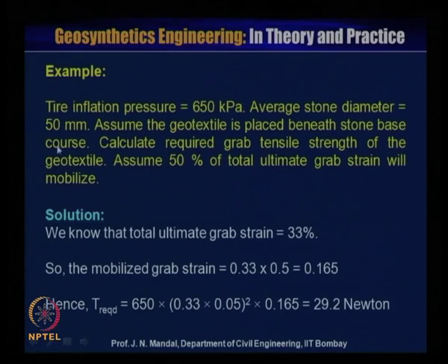So, 0.33 into 0.05, whole square, into the strain value. The strain value is 0.165. So, this will be equal to 29.2 Newton. So, from this analytical test, we can also calculate what would be the grab strength value.